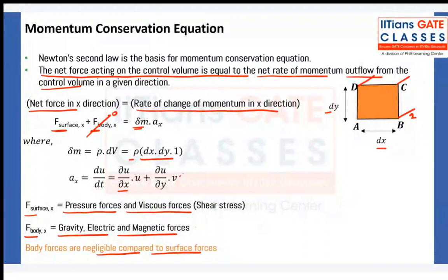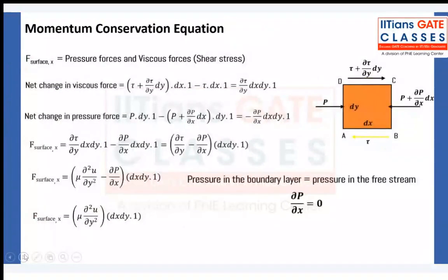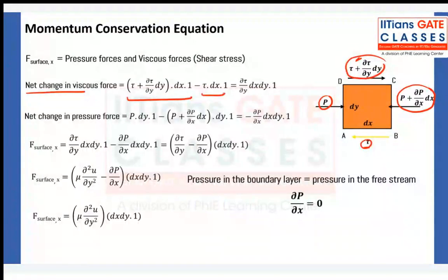Now what about surface forces, by pressure and viscous forces? Pressure forces are acting in this direction. These are compressive forces, so it will be negative. And these are shear forces: tau plus del tau by del y into dy. So net change in viscous forces is equal to this minus this, into area. So these are forces.